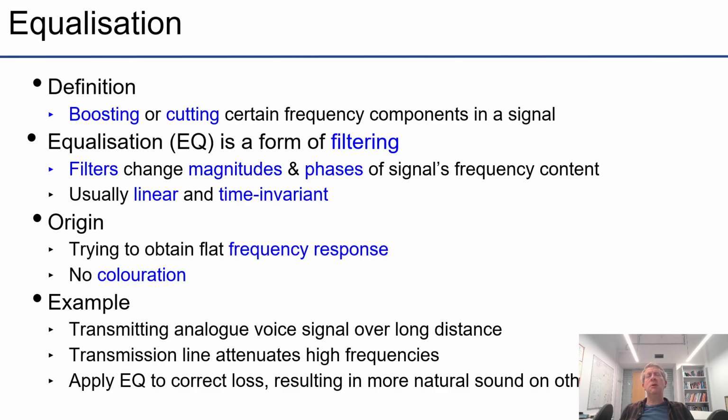And so this needs to be compensated for so that the spectrum of the output is as much as possible equal to the original spectrum of the input before traveling over the transmission line. And that's the goal here, often to obtain a flat frequency response. But now it's been extended and it's really any form of modifying and shaping the frequency response in a signal.